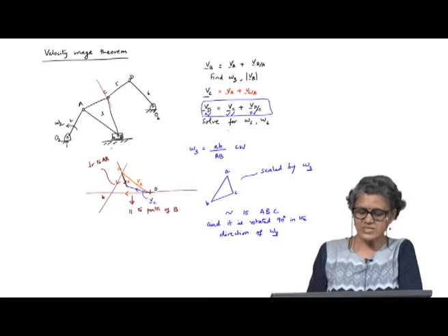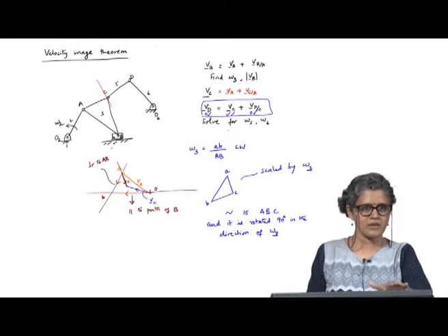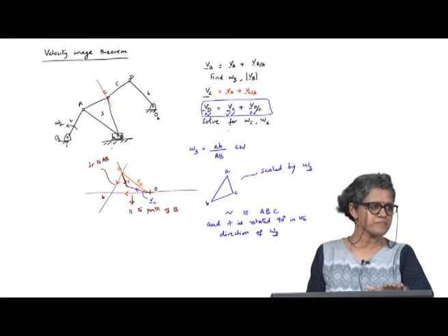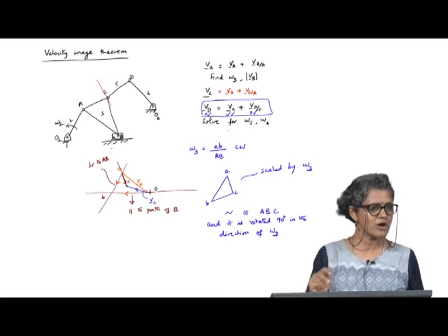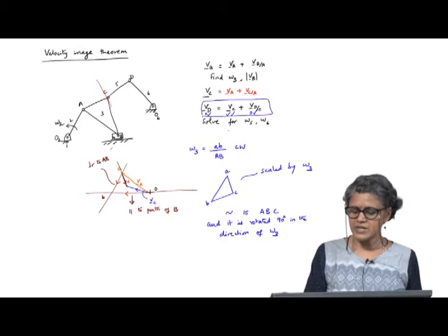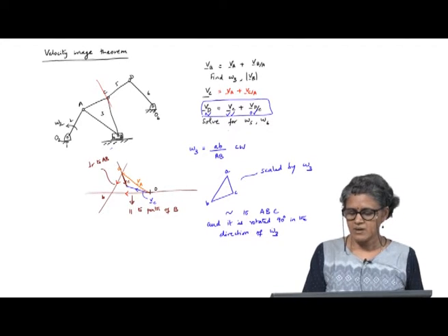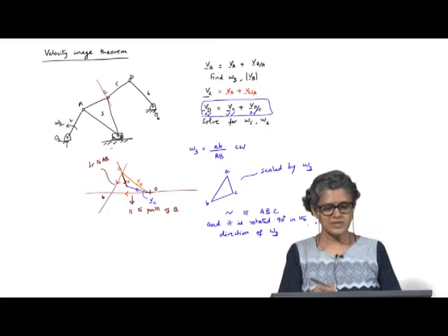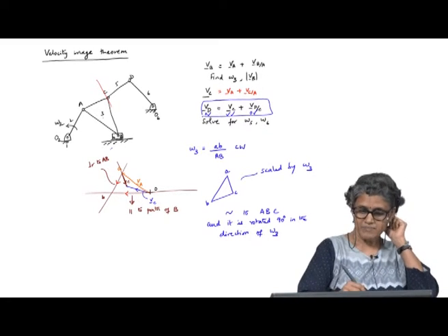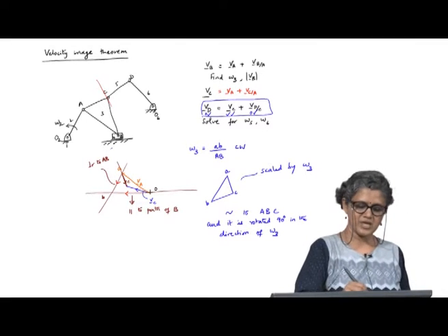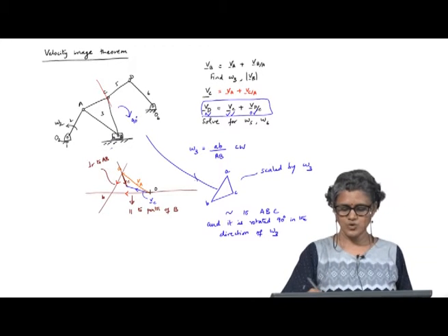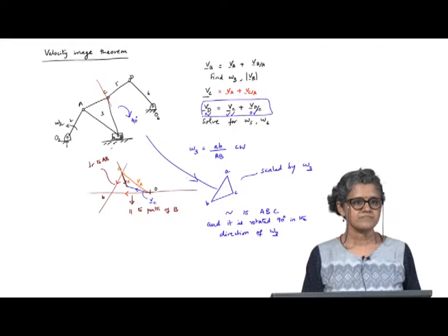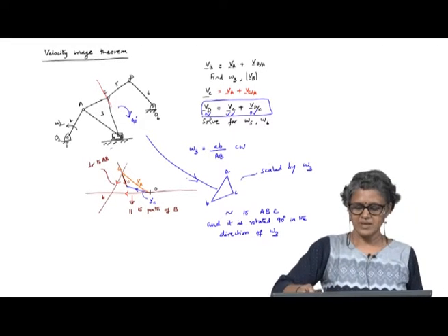That is what the, so the velocity diagram is an image of the position diagram of the linkage, okay, with all the relative velocities scaled by omega of the link and rotated by 90 degrees in the direction of omega 3. So, you can see here, see the order A. So, this is, if you take this and rotate it by 90, this is what you would get, and scale it. You can see C has moved down.